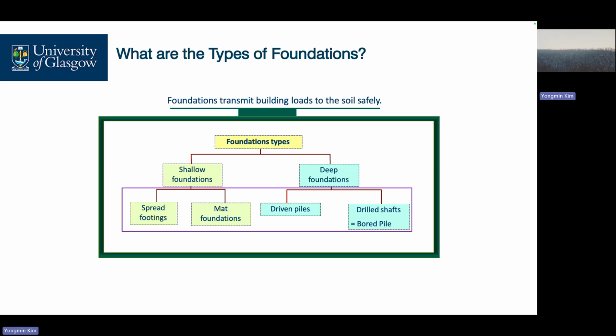But off the top of my head, I can say that driven is when a hammer hits and this pile is inserted. For drilled shafts or bored piles, we drill a hole first, then we put in our steel cage and pour concrete, then cast in place. So we have two different types of piles, driven piles and bored piles.